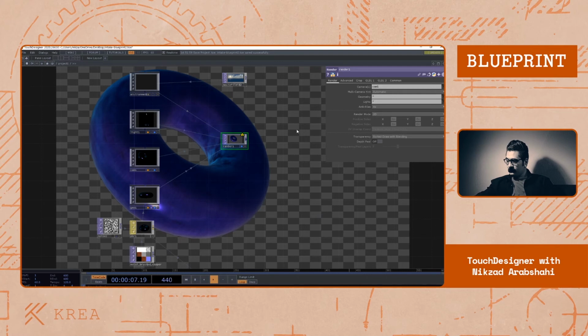You can add more cameras or lights or geo to the scene and decide which one you want to render just by typing the name of each component here. You can assign which camera, which geo, which light, or you can simply say all the lights, all the geos, and all the cameras.